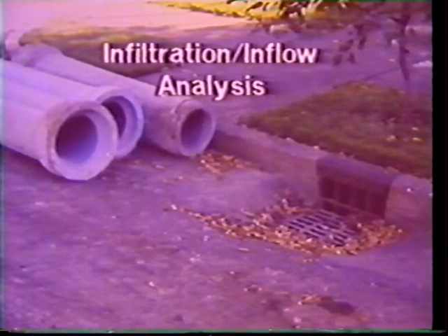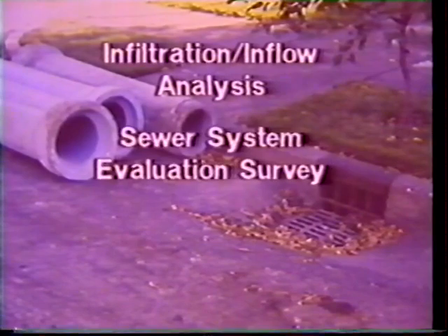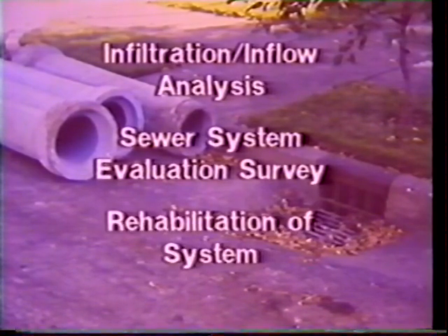That was step one. Once that's done, we have enough information to go on to the second step, the SSES, which is a sewer system evaluation survey. And then based on the information we receive from that, we can go on to the third step, which is a design for the rehabilitation of the system. And that's a sequence that you have to go through.